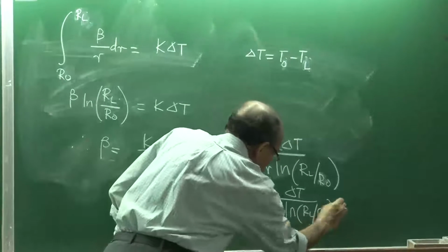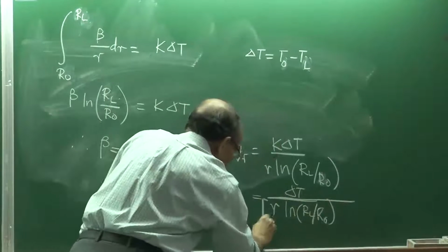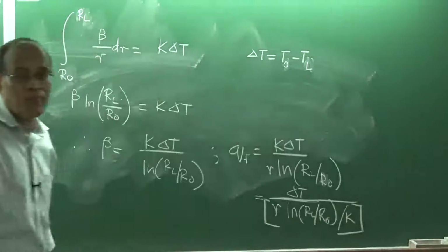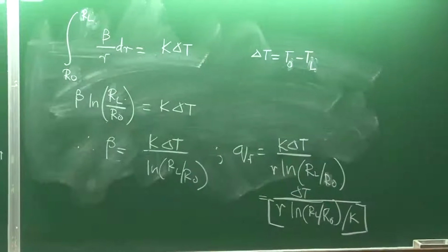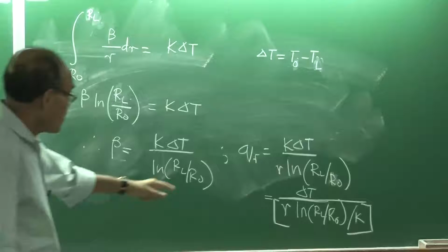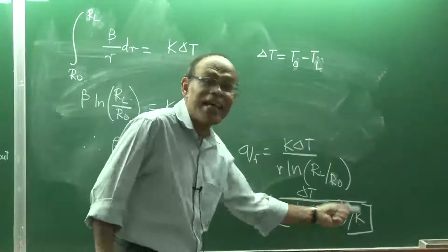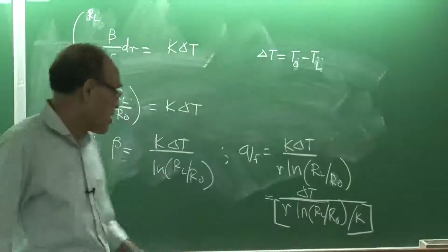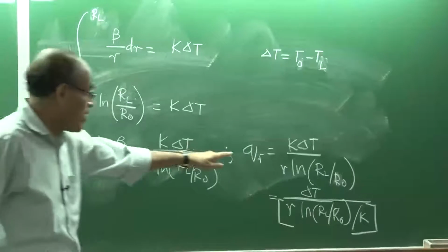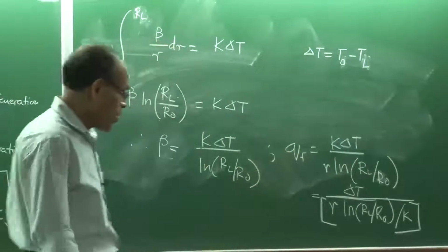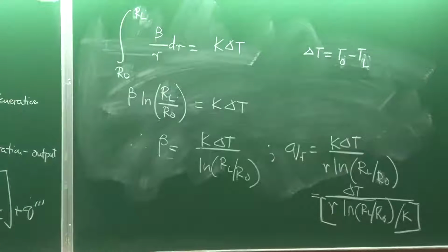So this is divided by K. Earlier, what was the thermal contact resistance? The thermal contact resistance was defined as delta x by K. That was the thermal resistance in terms of flux. So I have defined it in terms of flux. If I multiply it by area, in that case also I can do it. So there is no problem.